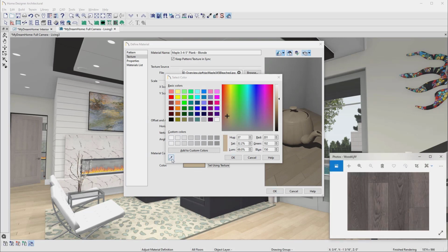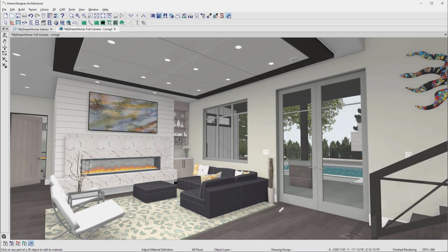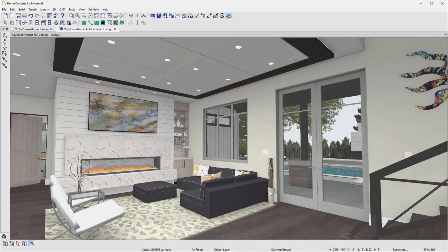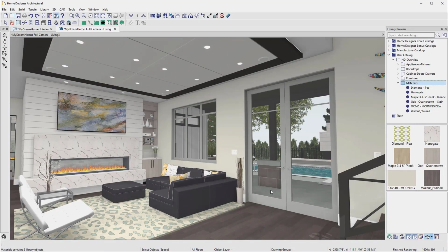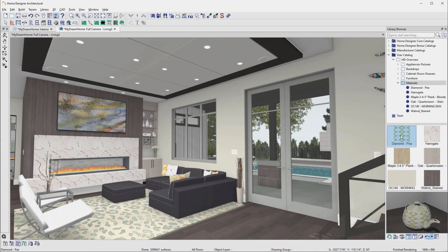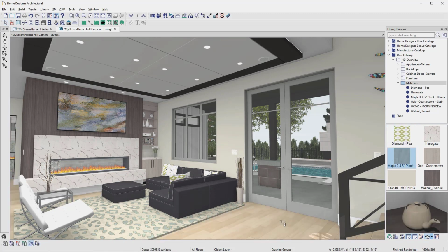In this photo with hardwood floors, use the Material Eyedropper to select the material, apply the color to the design, and then color blend the wood to create a custom color. Color blending is similar to a stain. The transparency can be defined to create a custom look. The Material Painter can change wall coverings, fabrics, flooring, or any element in the design. There are thousands of selections built into the software. It's also easy to import new materials.